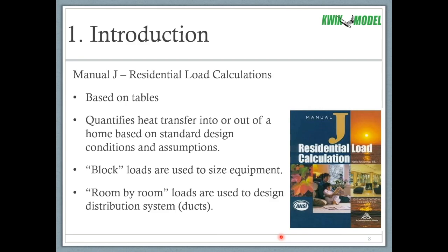And there's two basic types of calculations that you can do. One is called a block load, and that's basically the entire house or the entire zone that will be served by a single system, all done as one single heating and cooling load calculation. But if you're going to design the ducts for a house, you really need to know how much air needs to go into each individual room. And to do that, you have to do room by room load calculations to determine how much is the load on this room compared to this room compared to this room, and so on.